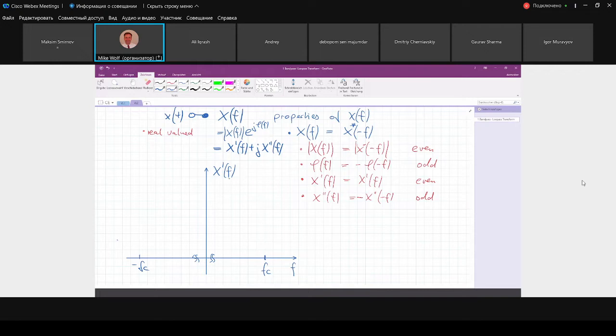I just want to show, let's say the real part of the spectrum would look like this. It would be a Gaussian pulse. And we know this real part of the spectrum. If I know the right-hand side, I know the left-hand side. There is no new information, but we need the left-hand side to ensure the inverse Fourier transform gives a real wave signal. So we use complex waves.